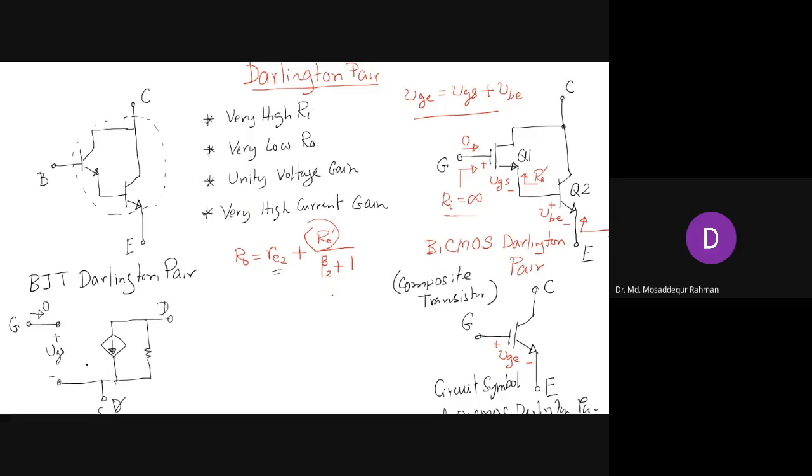And the current here will be gm VGS. So that is the current that is flowing into the source from drain. And resistance here is ro. So it looks similar to what we have for the bipolar junction transistor. We have the same structure, but there we have R pi. That's the only difference. Otherwise, everything is similar.